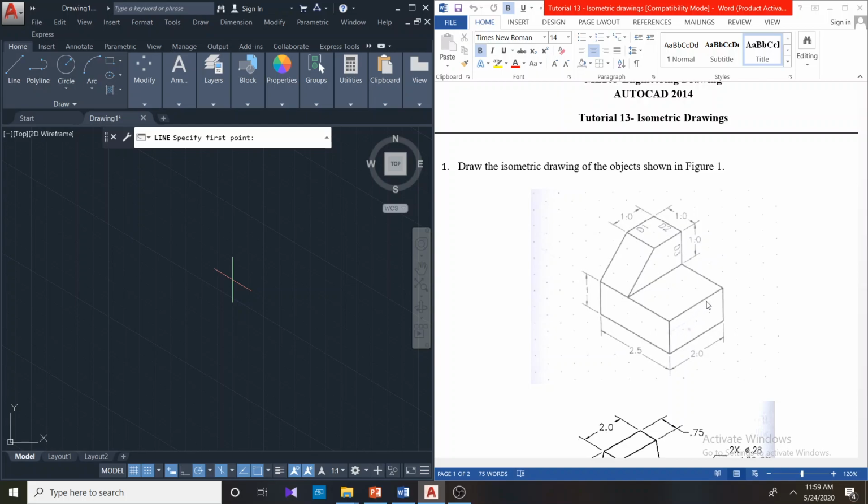This is actually in isoplane right, so we better go here and change the mode to isoplane right. This is not a must. You can even draw in isoplane left. This part you can draw in isoplane left also, but when it comes to circles you have to clearly select these planes. Better you select the plane and do it, then your grid has changed to the right view now.